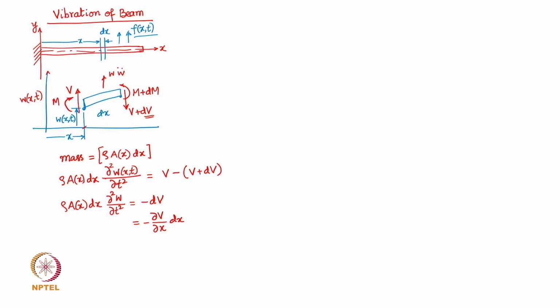That's how this equation is leading us to. Now if you take the moment balance about this point O, for an element which is under the action of all these forces, of course we'll have to see this as, if clockwise is considered positive, then the moment M will be the first of the moments about this point O, and then minus of M plus dM is the other one which is coming from here.